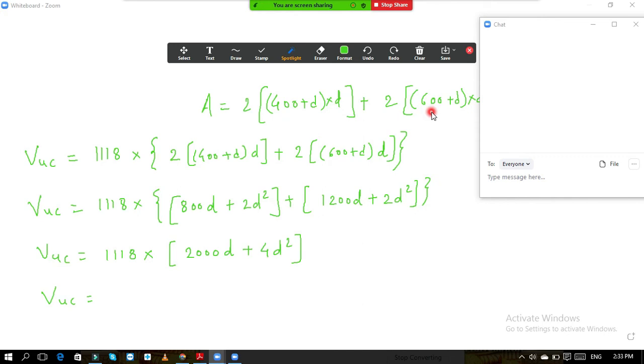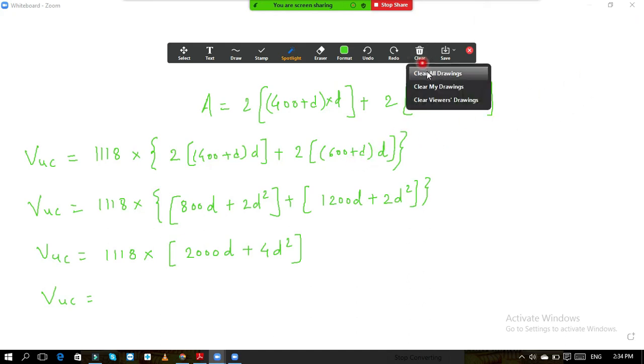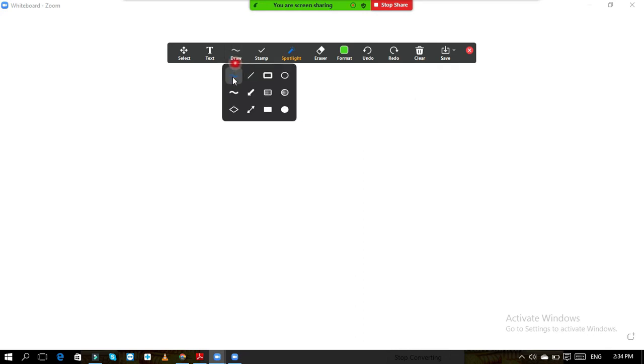Okay, I think in the previous equation number 1 also we have not maintained the unit properly. That is why this problem is there. I think so, because 400 and 600 are the units in mm, and here 118 is the intensity we have taken in kilonewton per meter square. So per meter square here we are taking, and here we are taking the dimensions in mm. So that is why we need to rectify this. Okay. So I will write the equations once again.